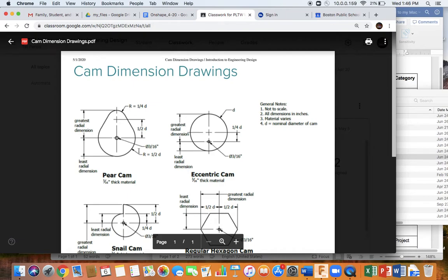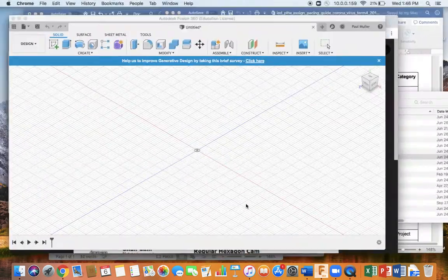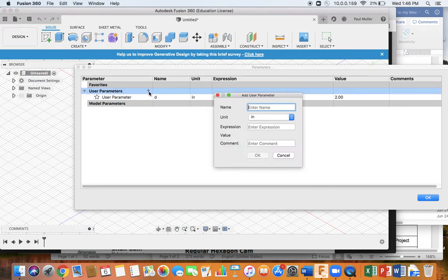All right, that's wonderful, but now we need dimensions for, for instance, this circle's diameter, this distance between two centers, the thickness, and then the sides of the square hole. So let's start off with, let's call this one D1. I'm going to click on the plus sign and type in D1. We could call it D small, whatever works for you.